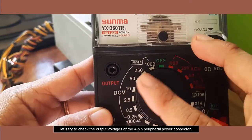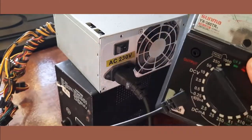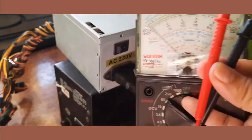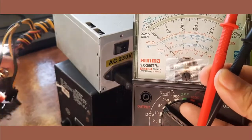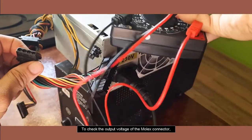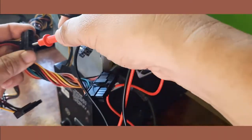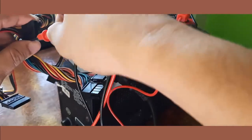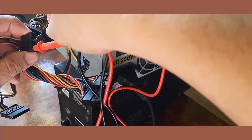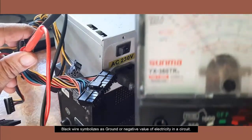Now, let's try to check the output voltages of the 4-pin peripheral power connector. To check the output voltage of the Molex connector, place the test probe in the appropriate color. Note, black test probe to the black wire. The black wire symbolizes ground or the negative value of the electricity in a circuit.